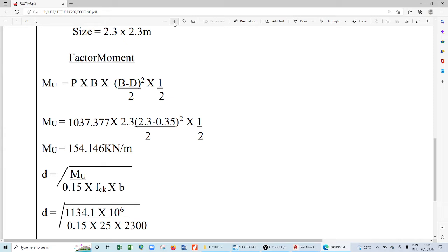So when you translate the critical punching area, meaning the answer you got, you add up at least minimum of 1 on either side. Get it? So meaning your first length, you would assume by calculating the critical punching area, add the 1 on either side and say that's my minimum size of that length. So now you will have the length.